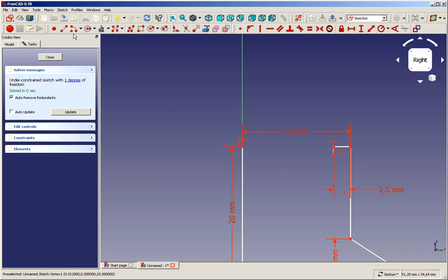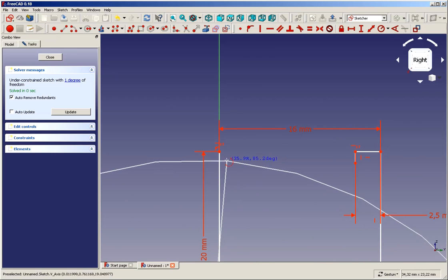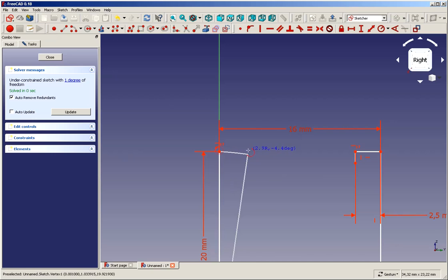So let's start creating an arc first. We need a center point, and we estimate the center point to be somewhere here. We will start at this point, and we will approximately go over to here. These 2 points shall be coincident to close our mixed polygon, so we make them coincident.